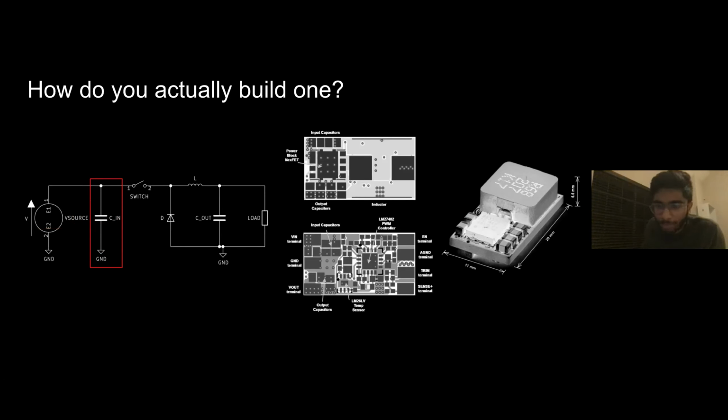Why do we use a 12-volt battery for boards that operate at 5 volts? Are there components that operate at 12 volts? So yes, a lot of components on our electric vehicle operate at 12 volts. Some of our sensors, some of our buzzers, some of our lights, LEDs. Also, 12 volts is the industry standard for car batteries. So that's kind of like a cool parallel that we have between actual industry and our race car team. Cool. So back to here.